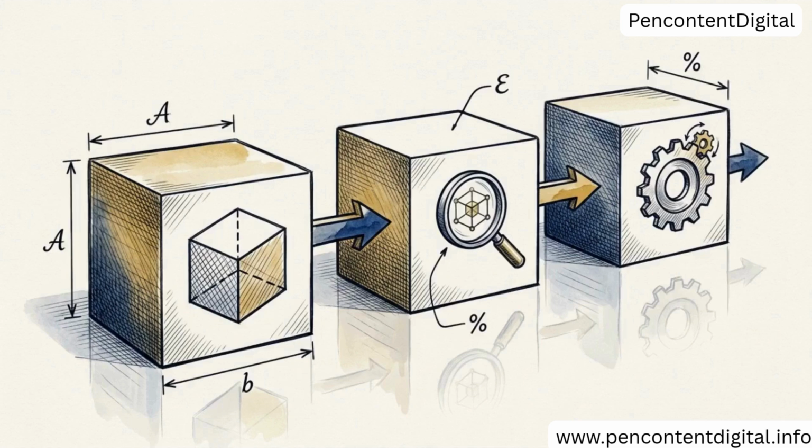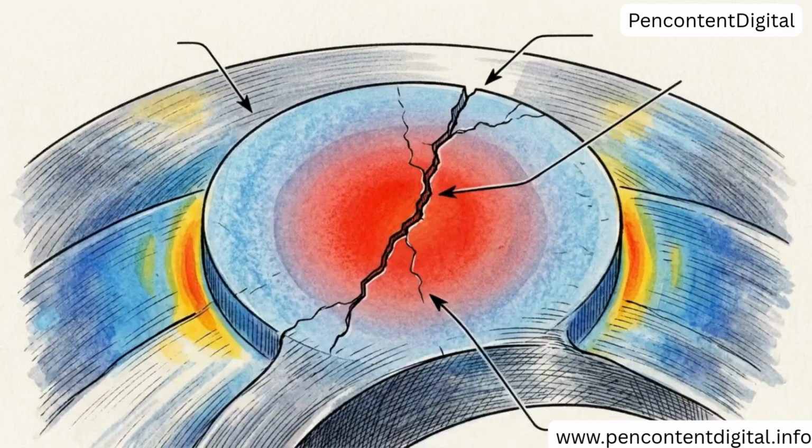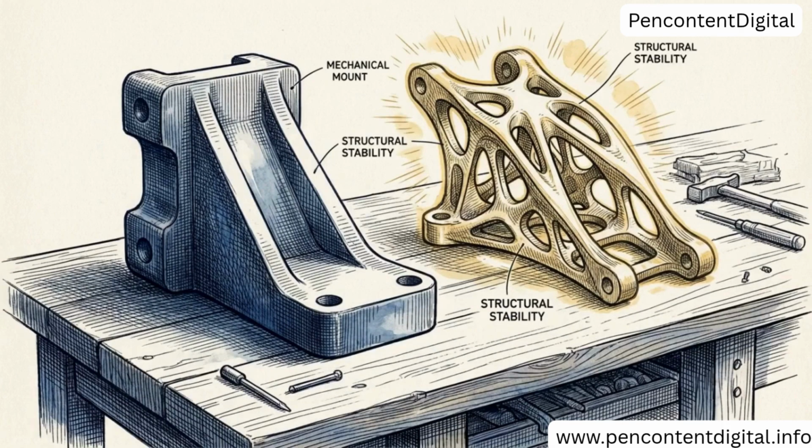This data flows directly into Step 6, analyzing results, and Step 7, optimizing the design. By identifying the red high-stress zones, an engineer can pinpoint exactly where a rotor is likely to fail during a high-speed stop. FEA empowers engineers to reinforce weak points or remove excess material to save weight, with the confidence that the part will perform as predicted.